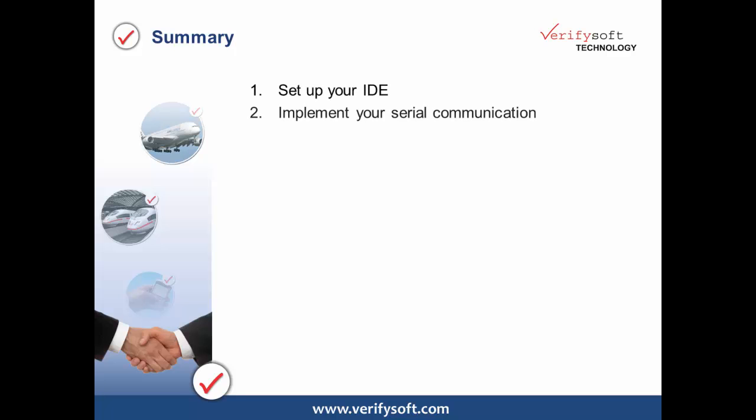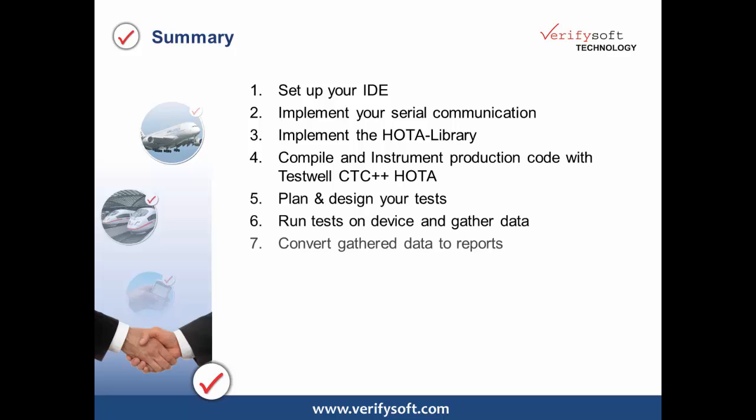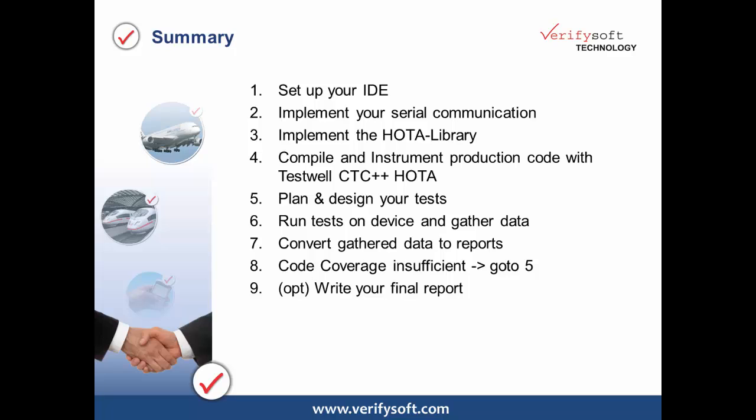To begin with, I will show you a short summary. These are the 9 steps we will be using to gather our data and analyze how well we have done our tests regarding code coverage. First, we have to set up an IDE. In this case, we are setting up, as an example, the Code::Blocks IDE with the AVR GCC of version 3.5 provided by Atmel. The next step would be to implement a serial communication.